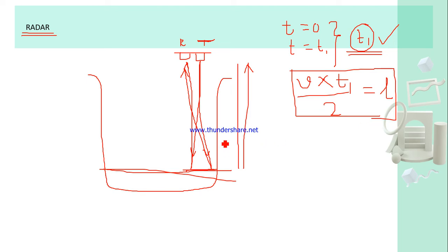now the thing is this angle, because when you are generating the pulses, this angle is called the divergence angle. So this angle should be as low as possible, otherwise it will spread out, and while you are receiving it, the intensity of the receiving echo signal will be less, which can cause some error in the measurement.